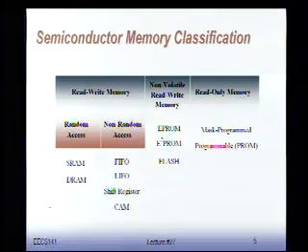So you put SRAM close to the processor. That's what the level 1 cache, level 2 cache, level 3 cache are. Very often they're all in SRAM. And then the DRAM is basically to store your programs. When you load a program out of your disk, you put it in DRAM. Okay? So that's the main differentiation between the two.